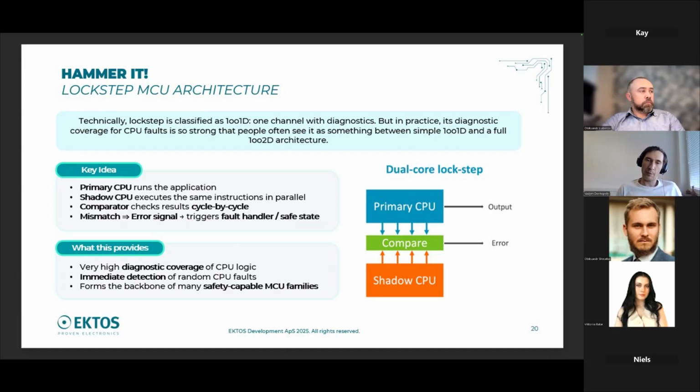And these parts are built inside the MCU. You don't need a heavy diagnostics routine to check the MCU arithmetic part or bus or whatever. It is much easier from a software perspective, and from a resources perspective, to perform your main core functions.